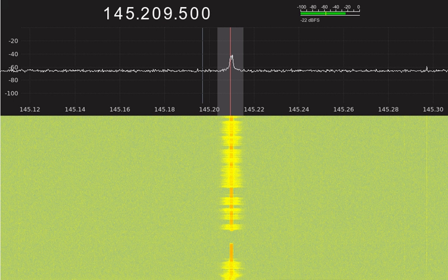What reading on an SWR meter indicates a perfect impedance match between the antenna and the feed line? A. 2 to 1. B. 1 to 3. C. 1 to 1. D. 10 to 1. C. 1 to 1.